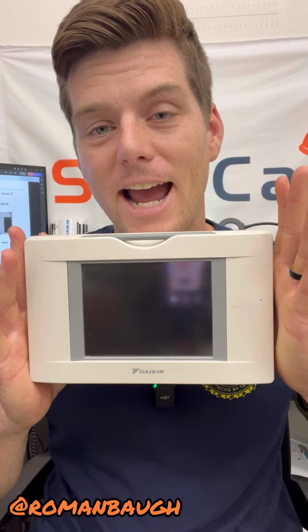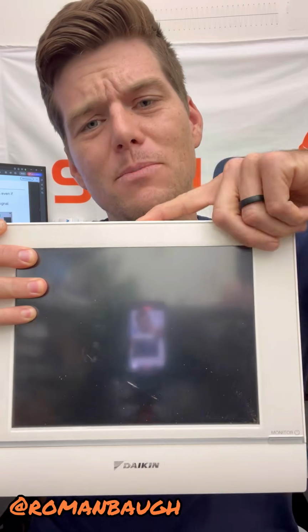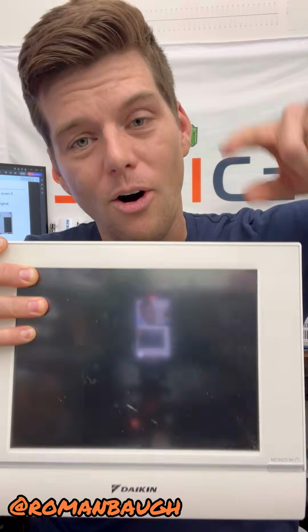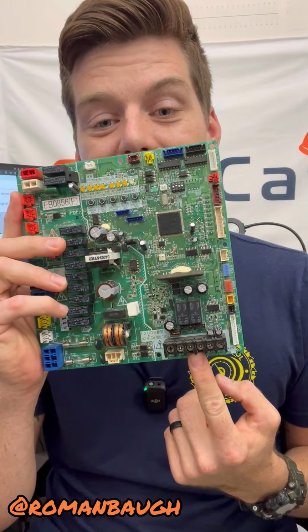Now, the other thing to notate here on this DC communication system, when we add a centralized controller, an ITC, or even an ITM, right? What happens? Well, this starts generating the 16.5 volts DC signal that then goes to the F1, F2 out on all the outdoor units, right? So this now becomes your main generation of your communication circuit, right? And so it's sending the 16.5 volts DC to the outdoor unit.